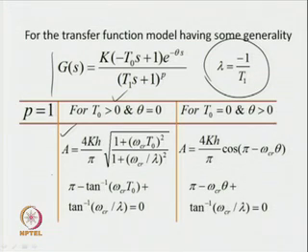Similarly, this we get from the loop gain condition, and similarly the loop phase condition enables us to obtain an expression of the form pi minus tan inverse omega CR T0 plus tan inverse omega CR upon lambda is equal to 0. So, basically we are able to obtain two relations, two equations using the describing function analysis.